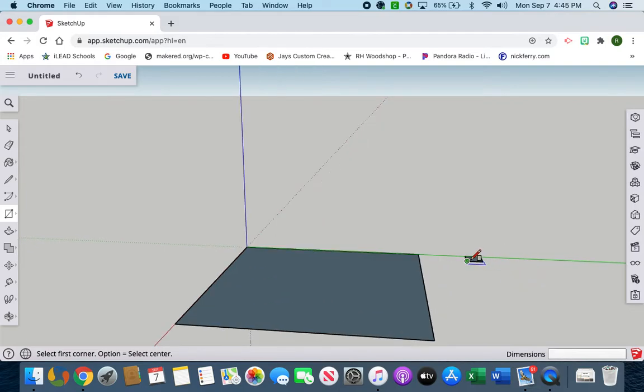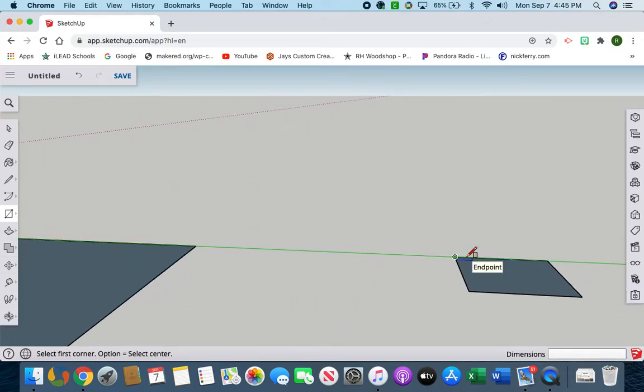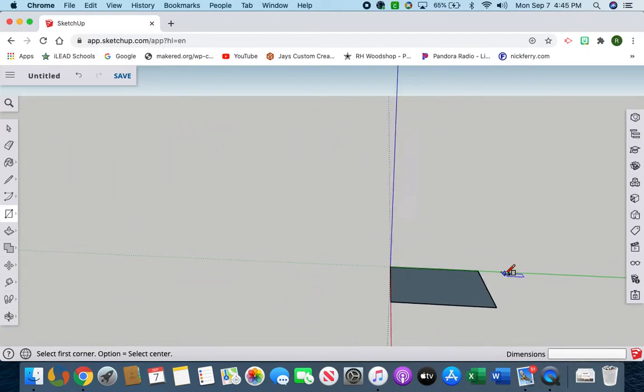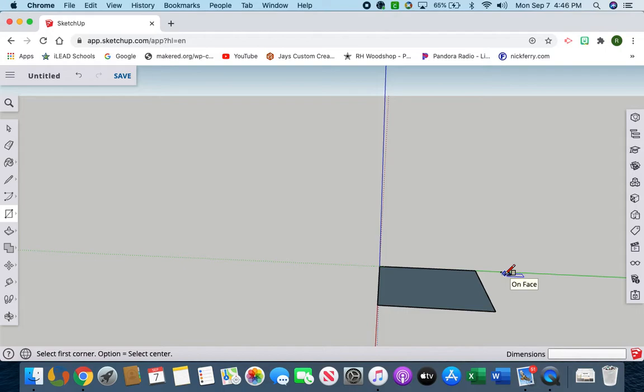So now I'm going to zoom in. It's again 2 fingers, zooming into where my mouse is. Big difference, this small square to this big square. So if you want something a certain diameter, you make sure you're putting in the right measurements. If you want feet, you have to put that apostrophe after the number. If you're going to keep it inches, then you just type in the number. I'm going to go ahead and get rid of that small square.